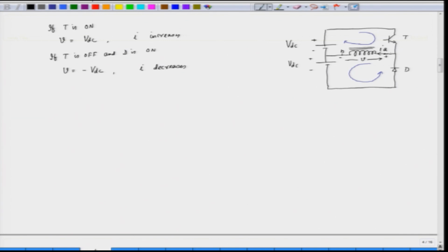Say we have this inductance in this case. So, V equal to VDC is equal to Ri plus N dφ/dt, the flux in the winding. Neglecting the resistance drop, because the resistance drop is quite small, it is a copper winding which has got a resistance also, we can say that VDC is equal to N dφ/dt.